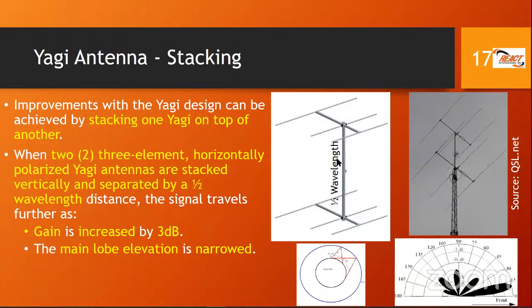Look at that. Are we getting something for nothing? Maybe, maybe not. But we are, as hams, looking to eke out every single watt of power and maximize its use. We don't want to waste it, and we want to direct it. And this is one way that hams do it. We stack the Yagis. And when you do that, the gain is increased by 3 dB. Just stacking these 2 compared to one antenna, you have a gain of an additional 3 dB.